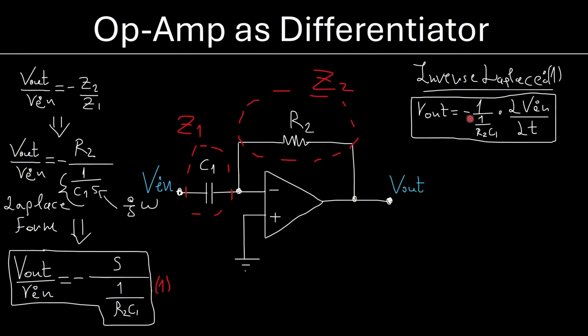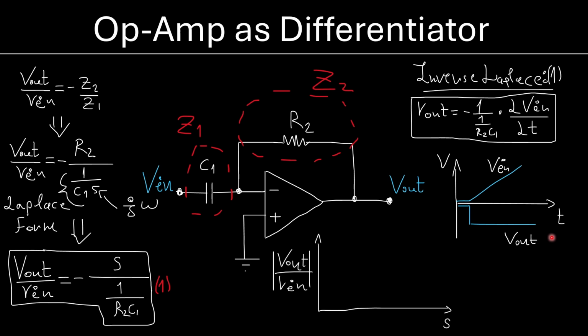Alright, obviously there is a minus sign here. Doesn't mean anything. It just means that the output signal is going to be inverse in respect to whatever differentiates the inputs. Alright, no problem. And now let's draw a ladder function for the inputs. Alright, something like this. And I can predict that the output is going to look like this. Alright? We seem that we have something that works.